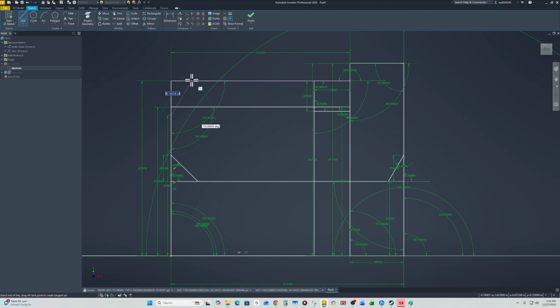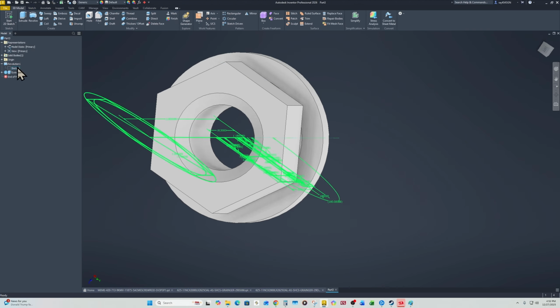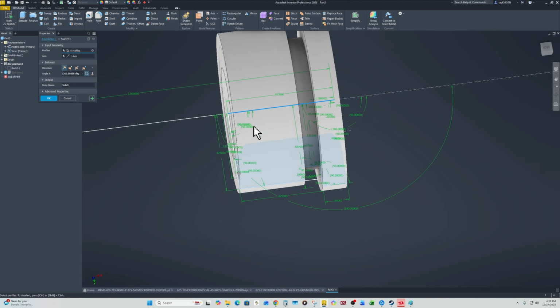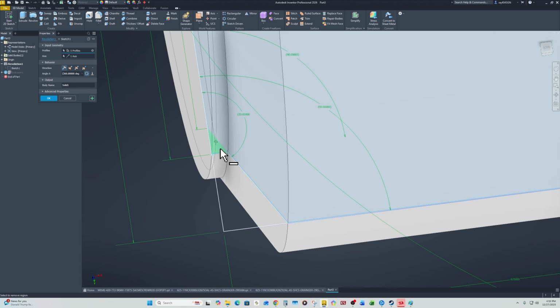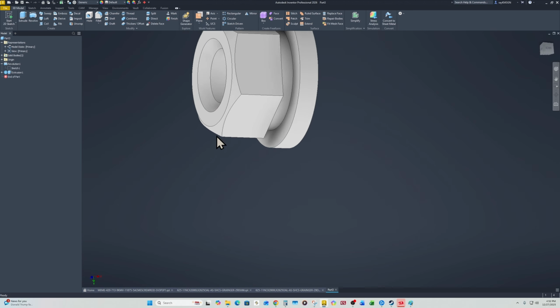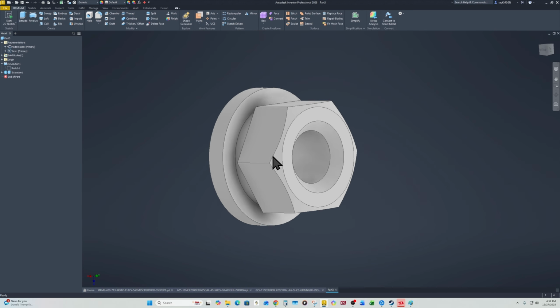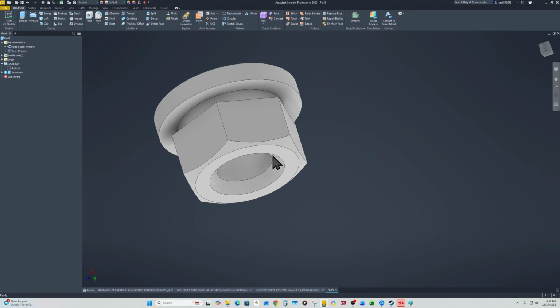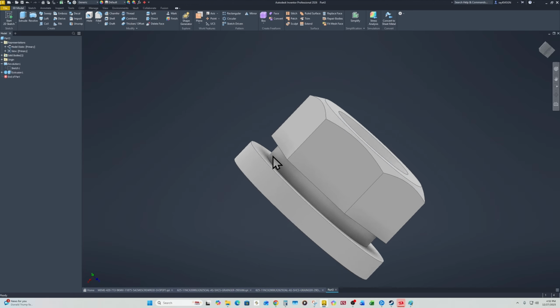Then I'm gonna do tab, I don't know, 150 degrees. Basically a 30-degree chamfer. Finish. Revolution. Gonna deselect this and deselect this with the control button pressed while I left click, and there we go. And that's how it looks.